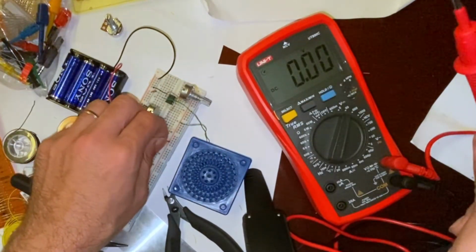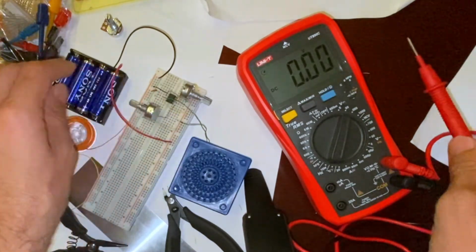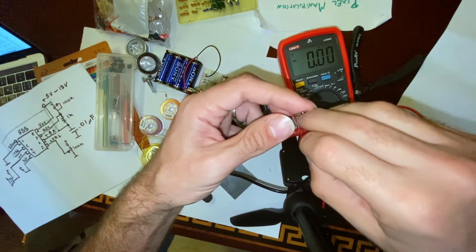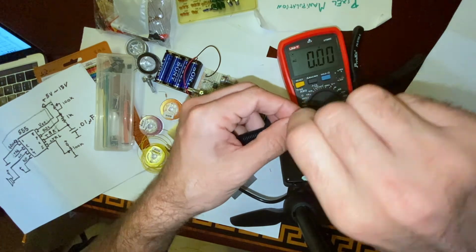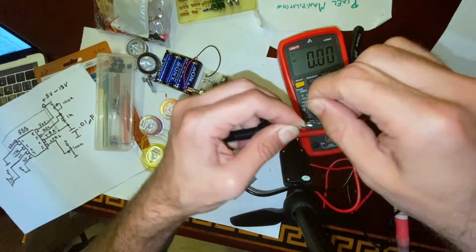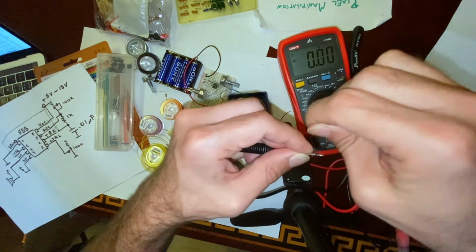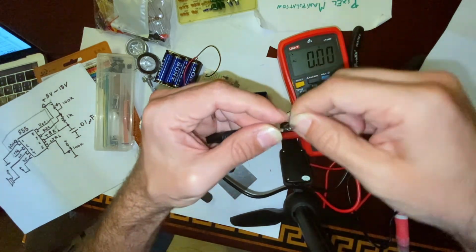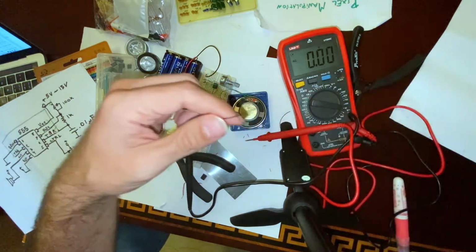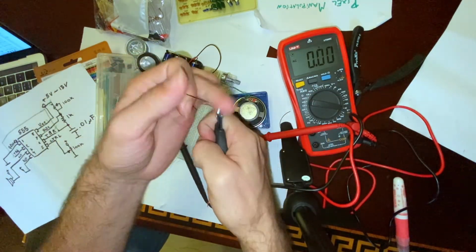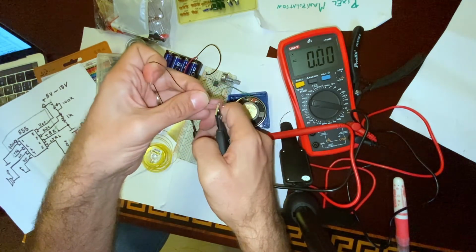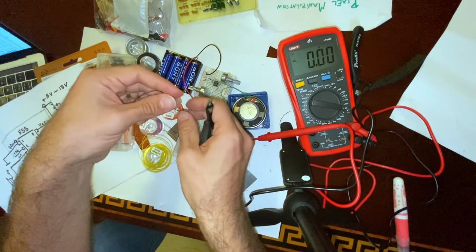It's 6.2 volts. And for the battery case, I get the red terminal connected to the power rail, and you will see here I have this little tip: when you need to move 3 things together, you have only 2 hands, you can wrap a cable around your voltmeter, and that, for example, in my case is the ground terminal. I leave it fixed and use the other tip to look at the output that is going to be showing us the frequency. So I peel off the other part and I insert it into the ground.